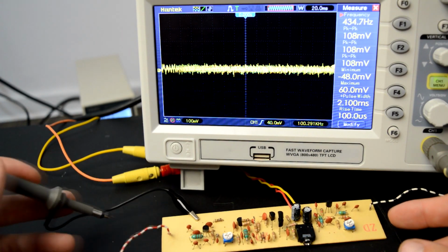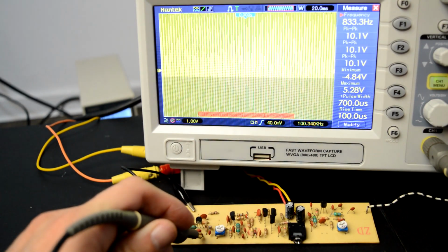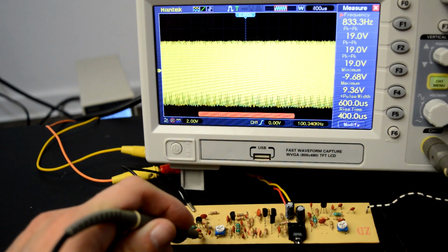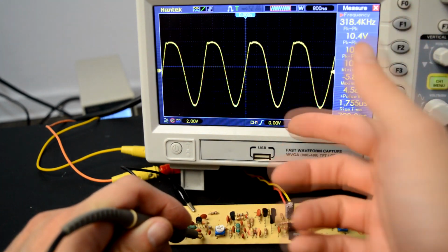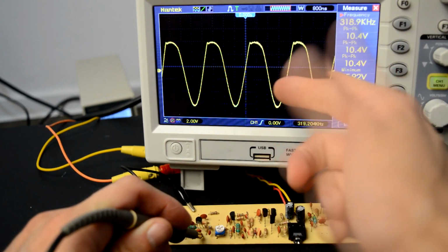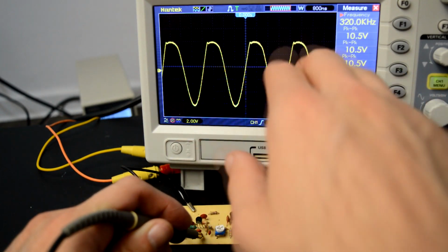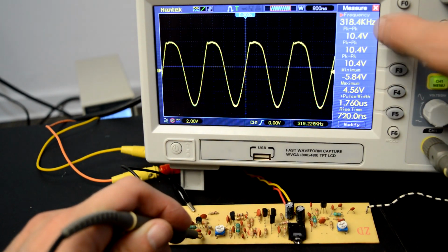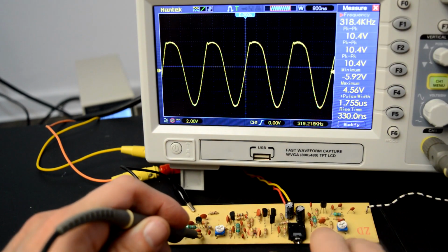in the simulation. First of all, we can look at the outputs of the oscillators, quite large signals, and we can see the basic shape that we've seen in the simulation. So the bottom part is quite sine wavy, while the top part is cut off, so it's a bit flat. And our signal is one of the oscillators at least at around 320 kilohertz.